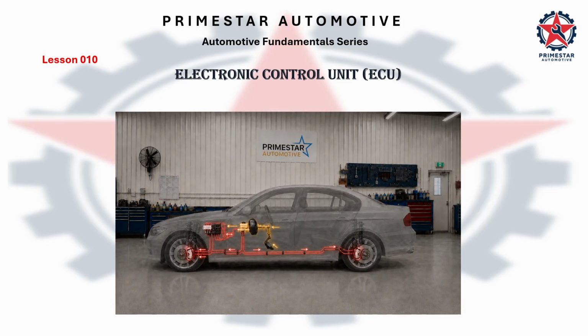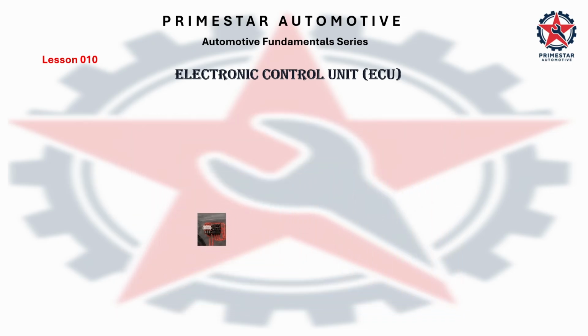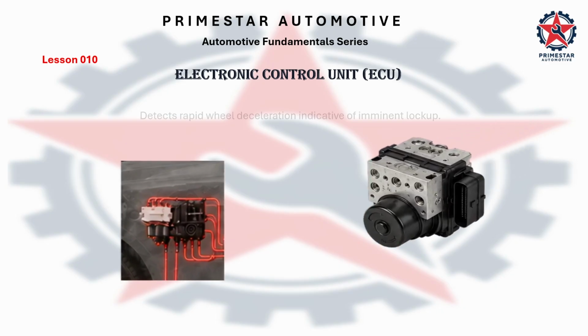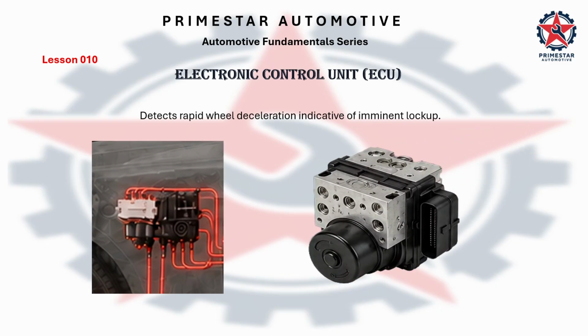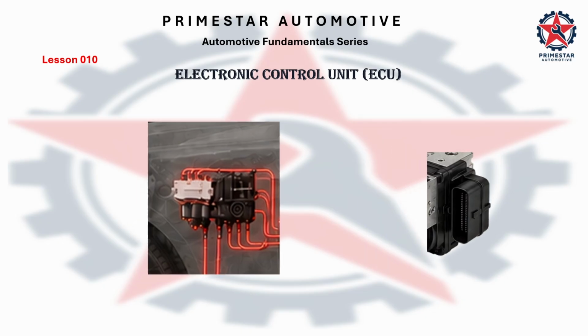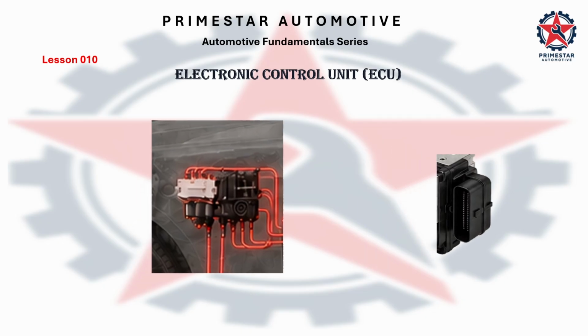Electronic control unit, or ECU, is located in combination with the HCU, or the hydraulic control unit. The ECU detects rapid wheel deceleration indicative of imminent lockup, and it is integrated with the HCU.